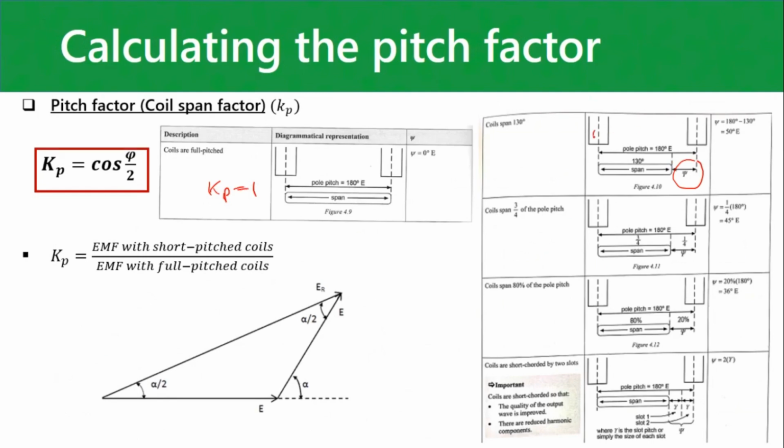But now here, let's take one example here. If it was here, and now the other side of the coil is there. Now, we say the coil spans 130 degrees electrically. But we know always between north and south is 180. But now our coil pitch is only 130. So this little angle over here, we are short by 50 degrees.